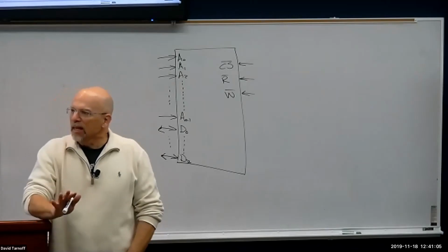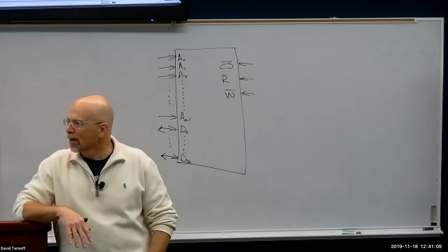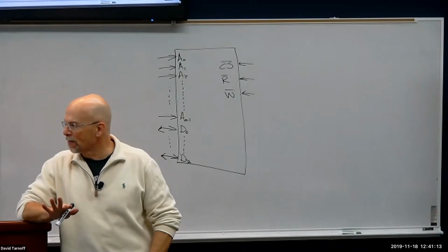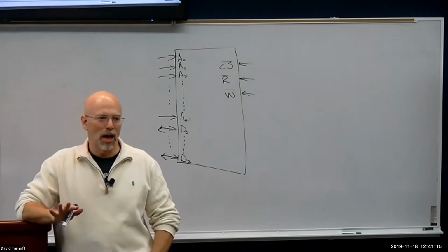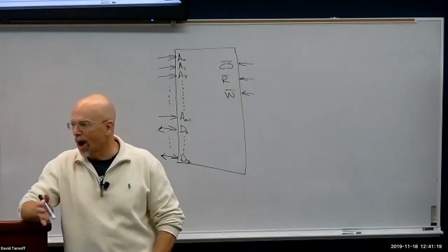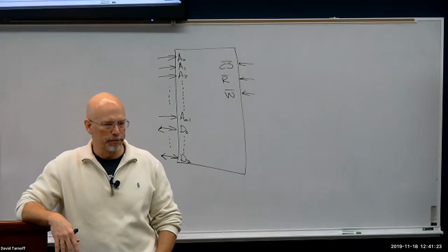And one of the things that makes reliability incredibly low is an increased number of connections. The more pins you've got, the less reliable the system is going to be. The more interfaces between devices, the more wires that are running between devices, the lower your reliability is going to be.